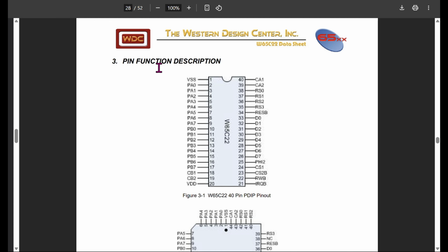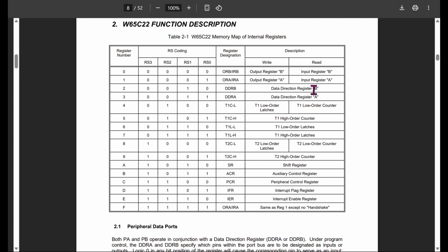So let's just remind ourselves of what a register is. A register is an 8-bit, in this case, number, which can tell us information, it can store a number, and it can tell the processor to do things. So, each of these registers, and here they all are, register 0 through register F, which is all of these pins here from 0000 all the way through to 1111.